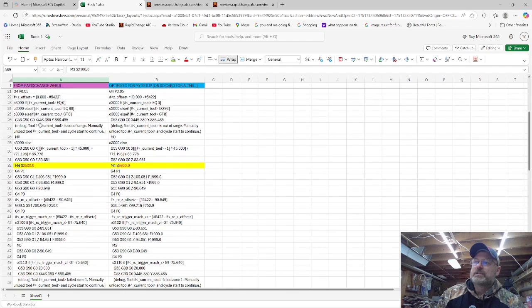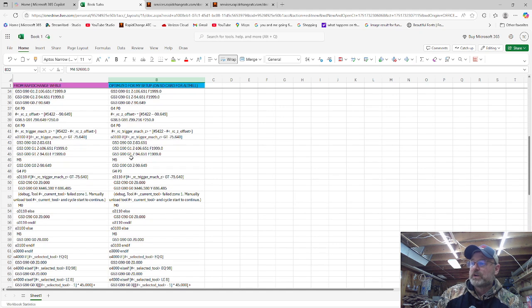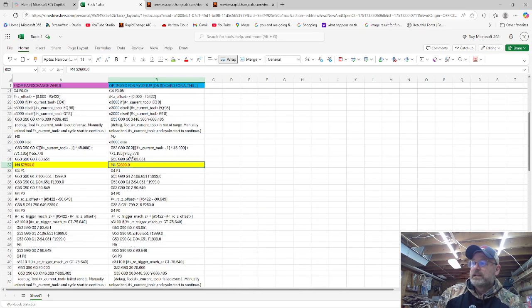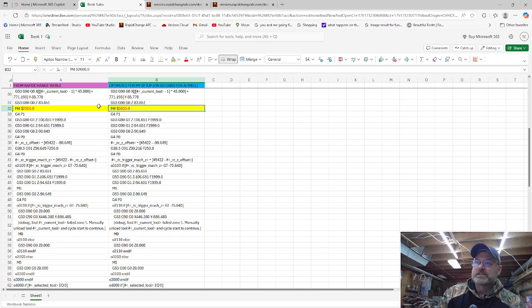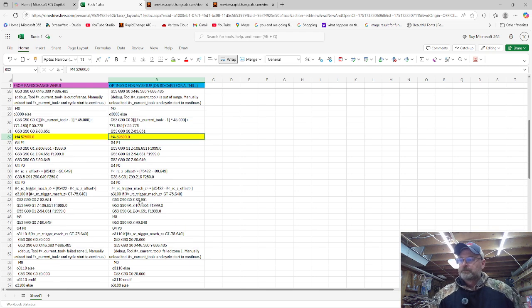It's automatically going to adjust the second speed in here. So for me, I adjusted mine to 2600 RPMs for unloading, and that's the only change that I've made. I just wanted to have a little bit more RPMs to unload it so that I make sure that it comes off of there. Typically the standard setting is just fine, but I up mine just a little bit.